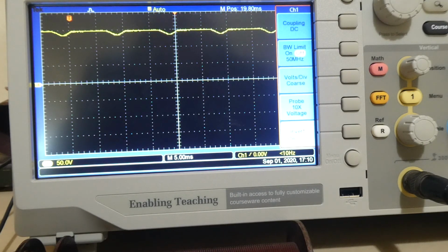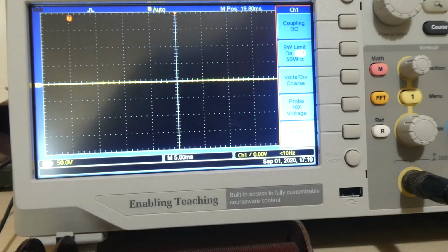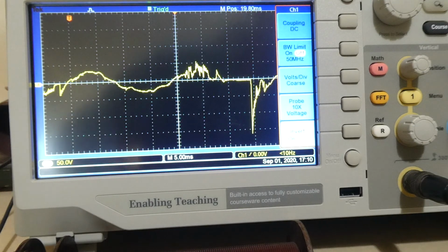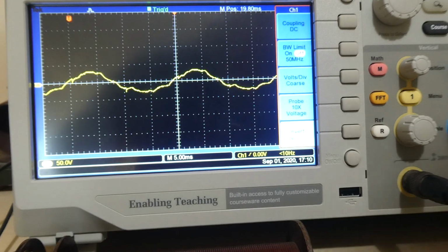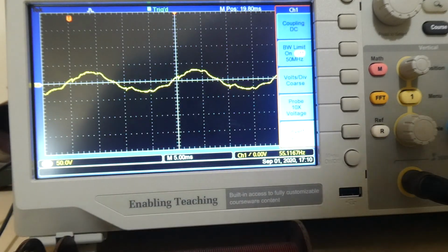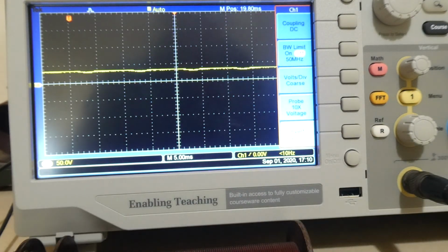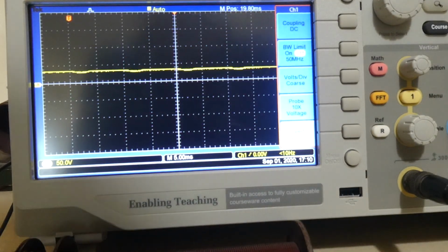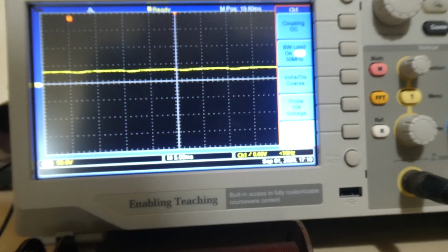Now I intend to operate the circuit with the coil switched in and move the oscilloscope position so that I can now monitor the voltage being produced across the circuit. Right, so with my probes switched on, I can now switch on and switch off the power supply.